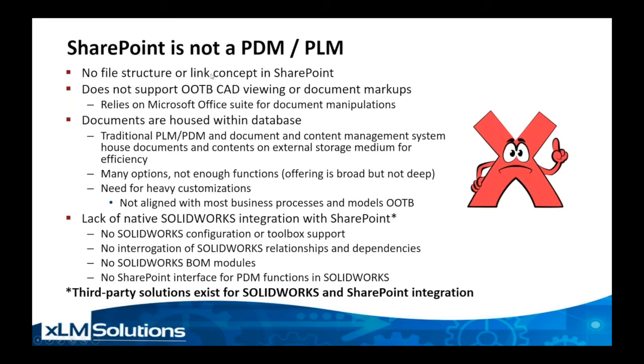So these are the key points why I say you should not be managing your SolidWorks data in SharePoint. First of all, there's no file or structural link concept in SharePoint. SharePoint doesn't understand an assembly that has relationships to parts and subassemblies, or a drawing that has relationships to parts and assemblies as well, or any other SolidWorks relationship. It does not support out-of-the-box CAD viewing. So if you wanted to view the SolidWorks file, you cannot natively view it within SharePoint. There is some redlining functionality, which makes use of Microsoft Office, but you cannot view native SolidWorks or CAD data within SharePoint.